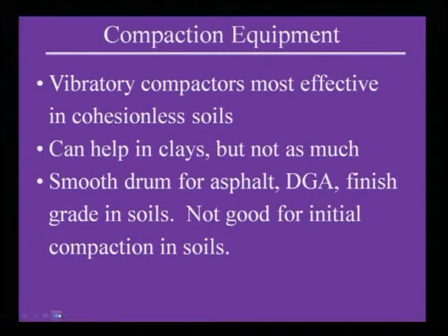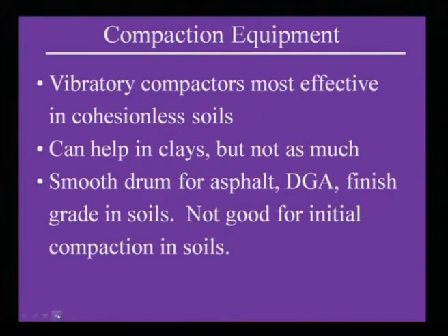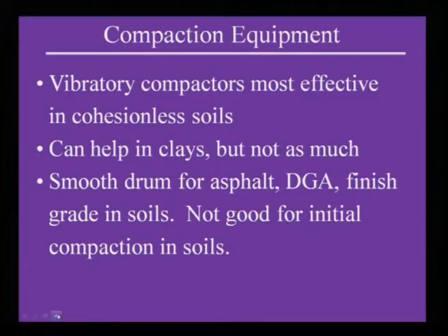Vibratory compactor, as I said, is most effective in cohesionless soil. I have shown you the vibratory compactor. It is most suitable for sand, which we call a cohesionless soil. Can it help in clay? Yes, it can be useful, but not as much, because clay has an adhesion factor. Some part of the clay soil will stick to the roller. To avoid that, the sheep foot roller is used.